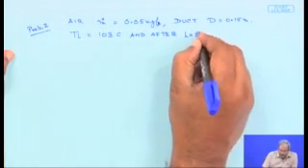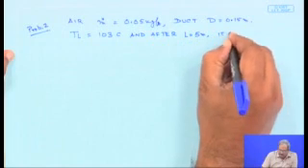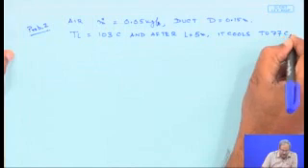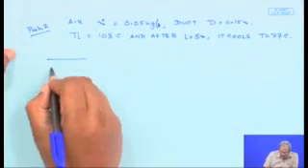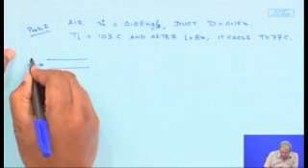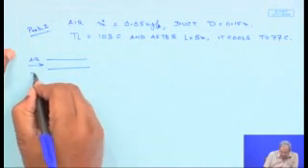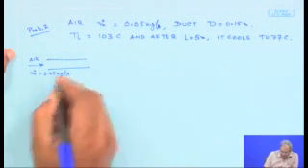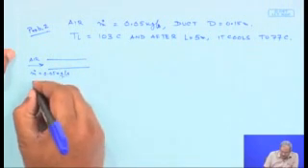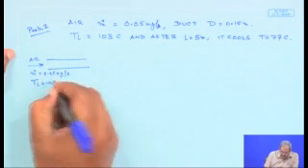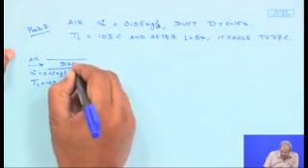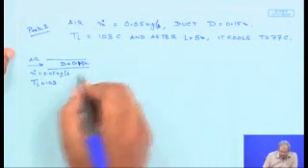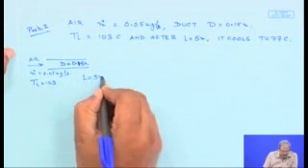and after L equals 5 meter, it cools to 77 C. So, this is the duct. You have flow of air, where m dot is provided as 0.05 kg per second. The inlet temperature Ti is 103, the diameter is 0.115 meters, and the length is 5 meters.